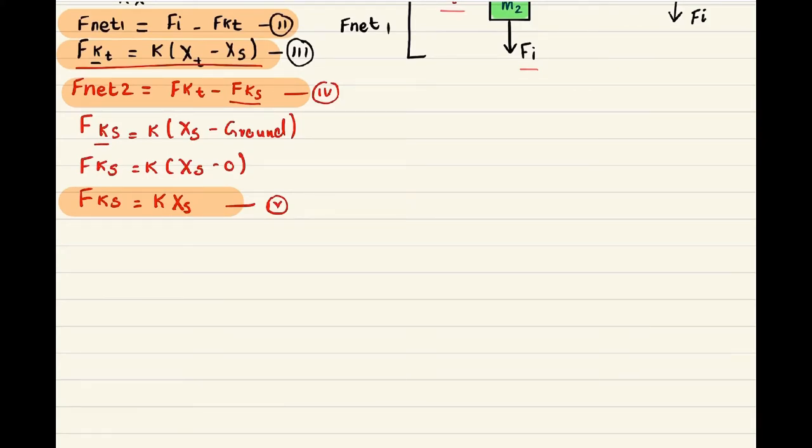So in order to draw the block diagram, first of all, I always say to start from the integral part. The reason is because we are having a displacement, and displacement is the second integral of acceleration, which means when we integrate an acceleration, we receive the velocity, and when we integrate the velocity, we get the displacement.